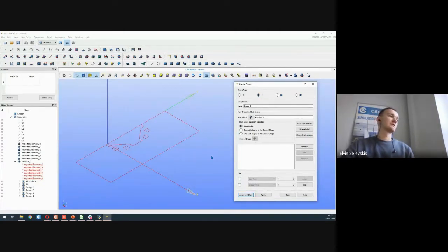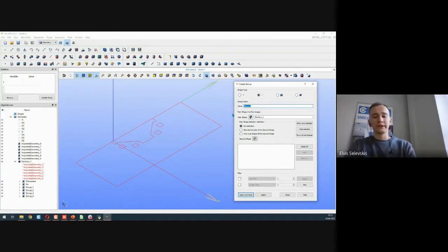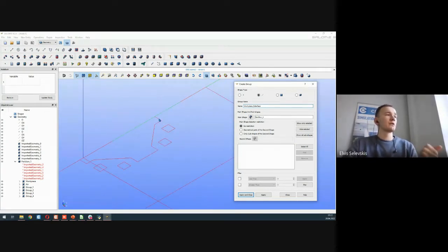So here, if I press on the lines, we can see all of the lines. As I said, the one which we'll start with will be the workpiece interface. If we zoom in, we can just click on all of the lines which are inside of the air domain. So this one, hold down Shift and select all of the ones which are inside of the system. As I mentioned previously, the one which is on the symmetry axis will be put in a different group.